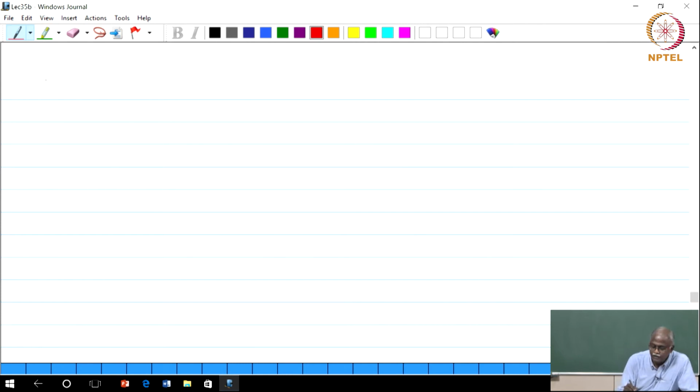So, the first task for us is to design block transceivers where there is no interblock interference. Basically, I want to use the redundancy first to eliminate interblock interference. So, take the general case that we have a channel model.